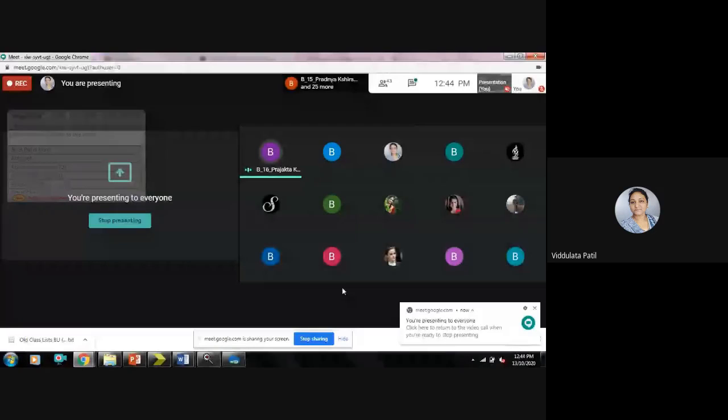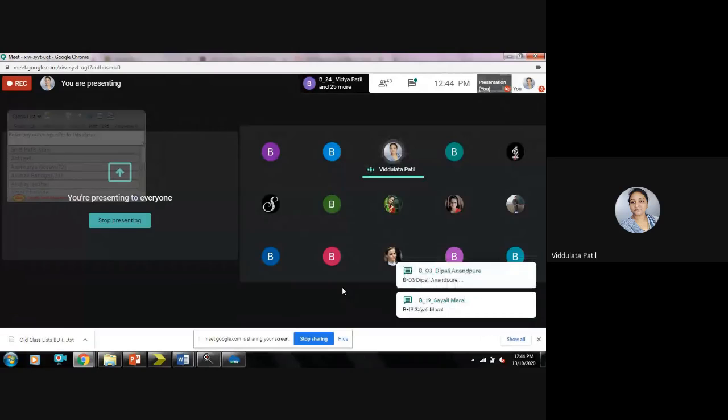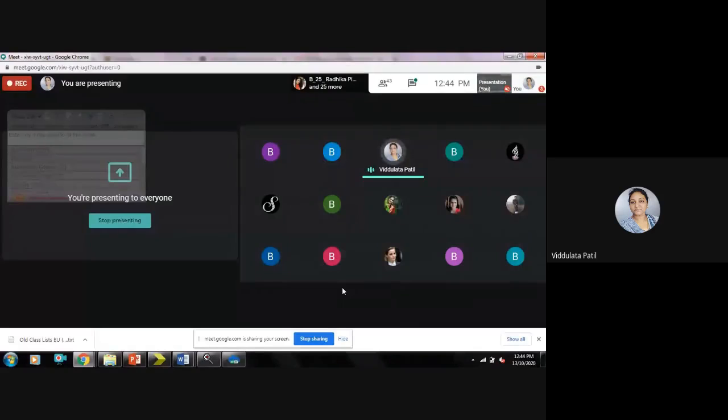So here, in a serial in parallel out shift register, the data input comes in a serial way. So if it is a 4-bit shift register, whatever the 4 bits are, they will come serially, and they will be available at the output terminals in a parallel way. That means there will be certain time required to load all the data, and only then it will come out. At each clock cycle the data will be shifted, and after that